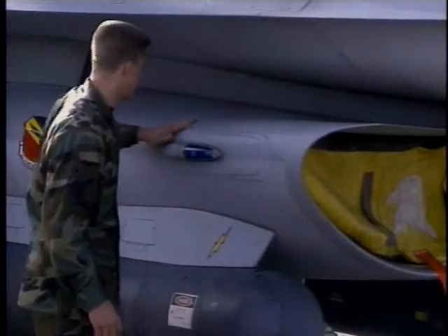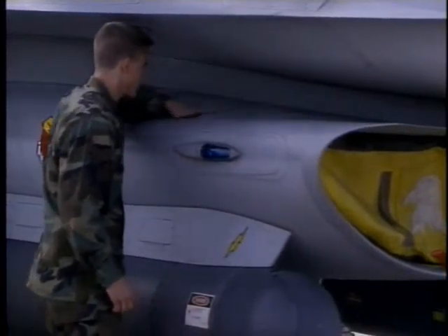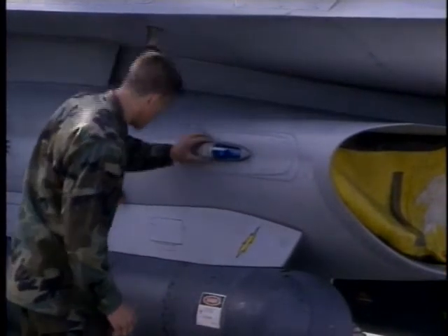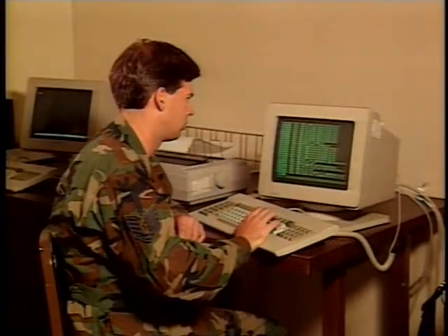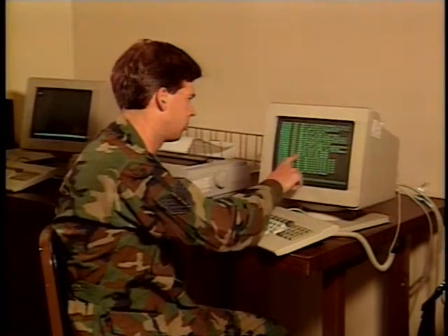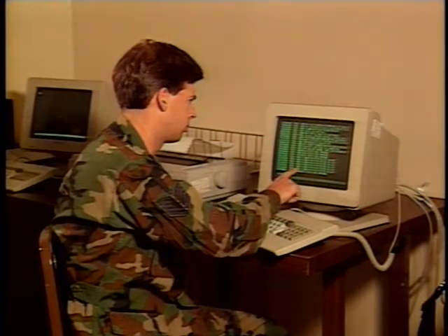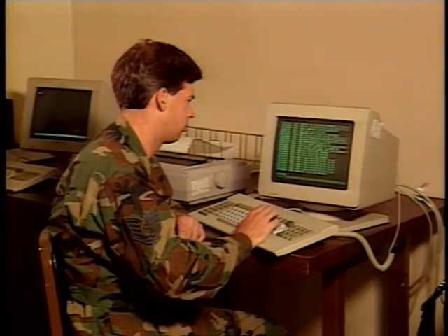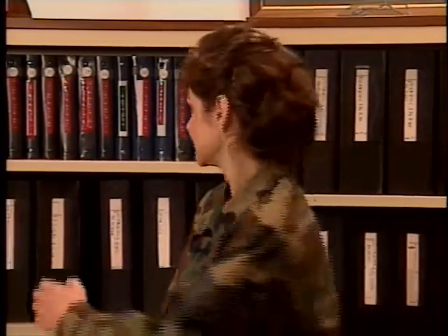The frequency and extent of aircraft and component inspections will be determined by the parent organization. However, documentation of the discrepancies should be standardized to avoid any misunderstanding and to adequately track any trends that may occur. If we identify a corrosion problem, how do we find out what the limits are on the damage? Let's start by looking in the applicable tech data.